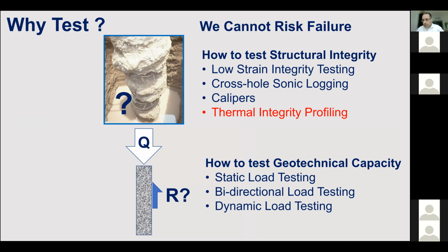For the geotechnical capacity, of course, we regularly undertake static load testing, or if the loads are quite huge, we do bidirectional load testing using embedded load cells, or even dynamic load testing, which can also be used to determine the capacity of the pile, including the shaft and end bearing resistance.